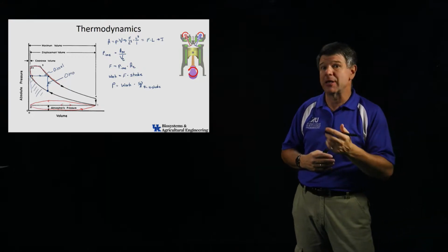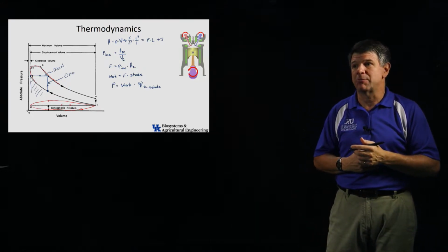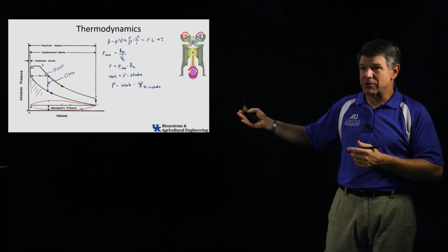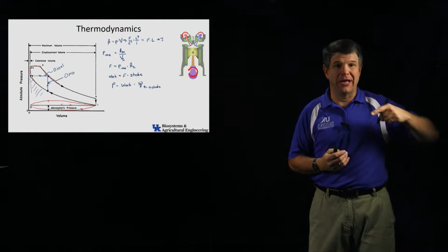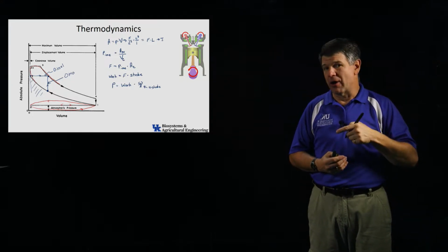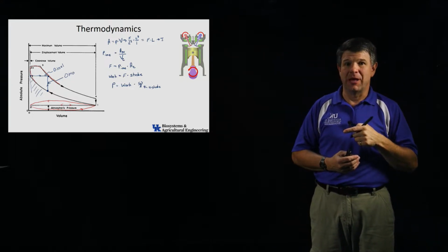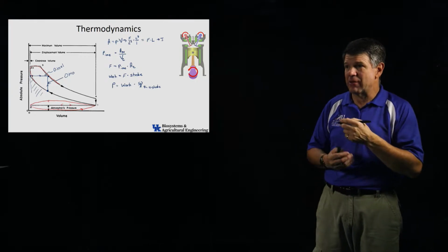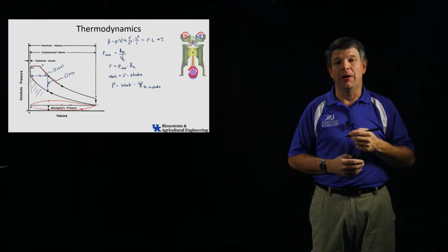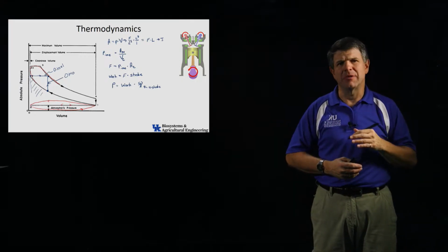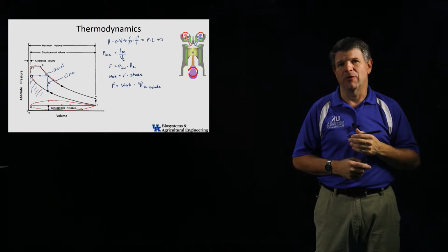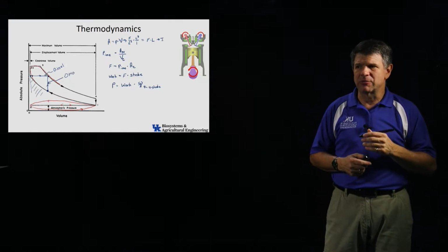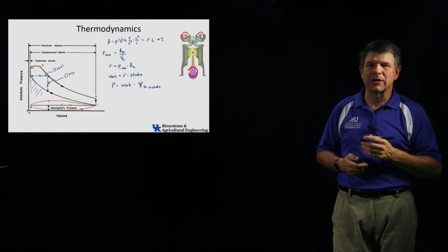Okay, and one of the things, again, we talked about turbochargers in the last module. That would be a case where instead of drawing a vacuum when that piston's coming down, I'm actually helping to shove the gas into that piston as it's coming down. So that's going to give me a little bit more pressure in there. So that's going to manipulate and change that curve and make it look more like the exhaust curve, therefore less losses. So there's a lot of things we can do, and that's why we look at that PV diagram.